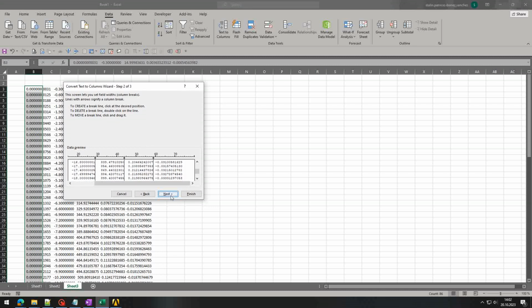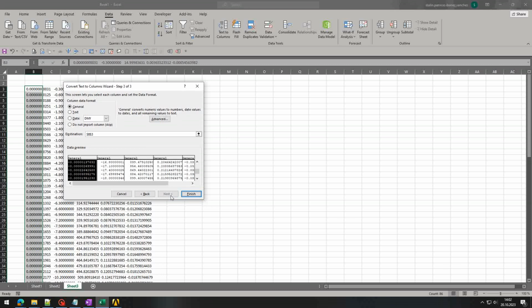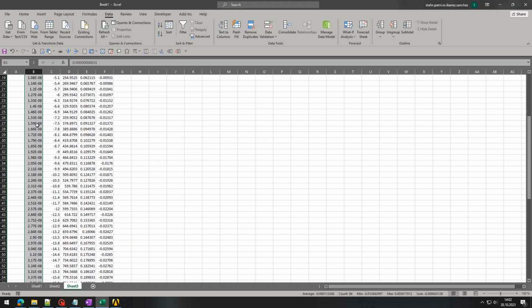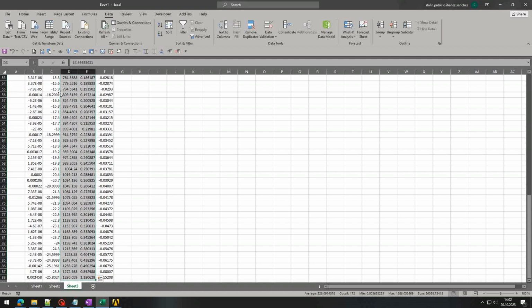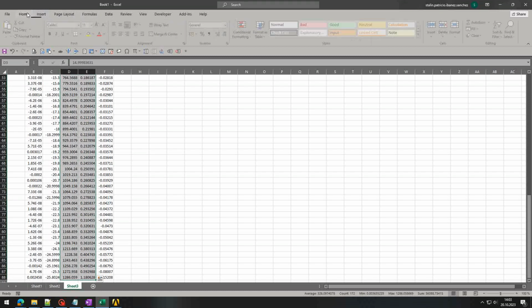So we are going to copy and paste them in that way, see what happened, and you see already that it seems to be working. So the first value was the force in X, or reaction X, reaction Y, bending moment Z, and displacement Y, and displacement Z. So we can now just add a plot with the bending moment and the displacement Y, and see how that looks.